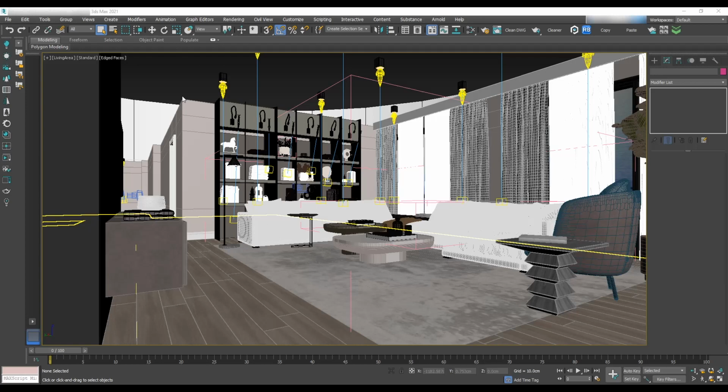To optimize the scene, we need to make proxies. In the Corona renderer, proxies don't improve rendering time. They do help keep a smooth viewport performance despite many objects in the scene though, and they help make the file smaller. First, we have to check the number of polygons for each object and make a proxy for any object that has more than 3000 to 4000 polygons.